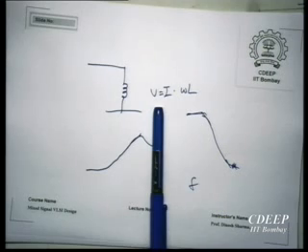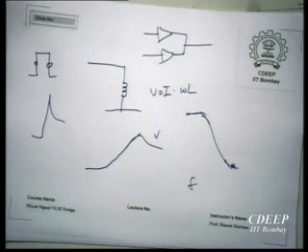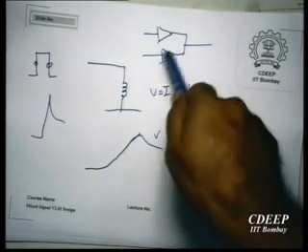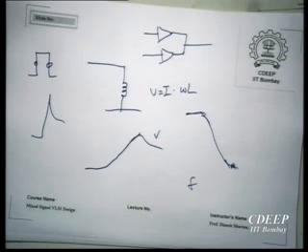you need to dump a huge amount of current, and during this time you have to withdraw a huge amount of current. So essentially you have a transient driver and a steady state driver, both driving the same line. This transient driver is very power heavy, a huge amount of current, but it is turned on for a very short amount of time. The other guy is a very easygoing low power thing, and its job is to maintain a 0 at 0 and a 1 at 1. In short, this is the low frequency amplifier, this is the high frequency amplifier, right?